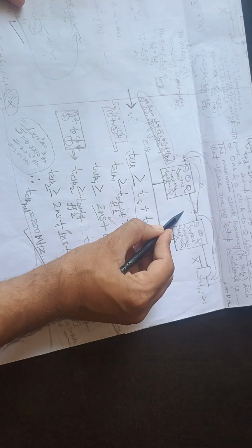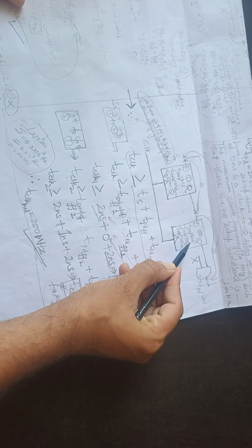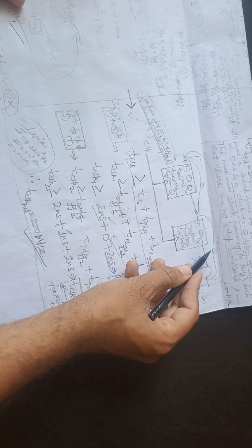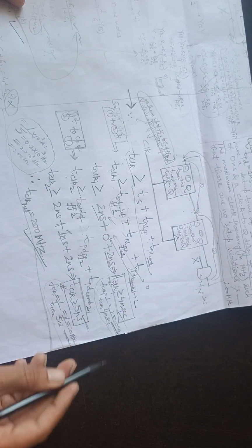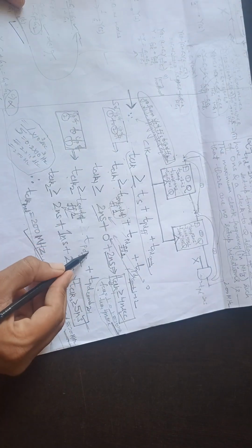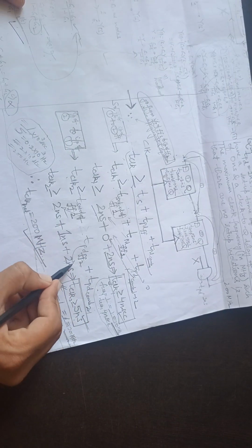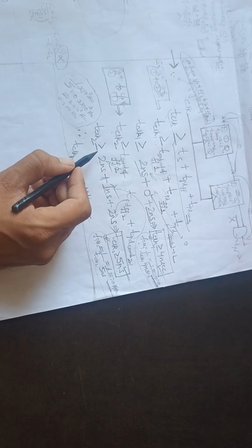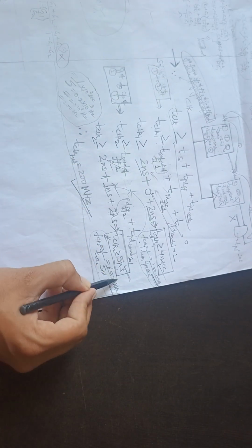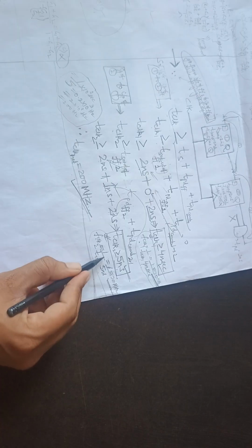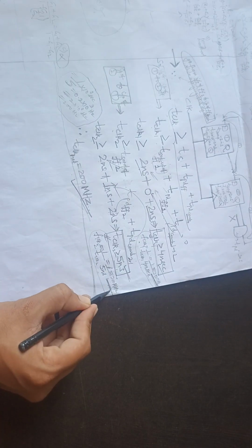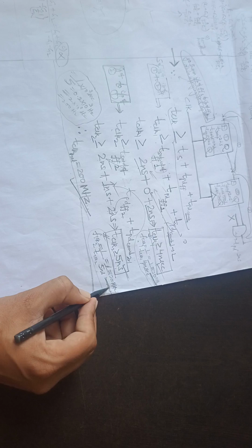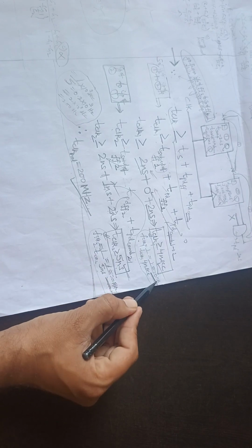Okay, and in the second case T clock 2 should be greater than or equal to the setup time of flip-flop 2 plus the propagation delay of flip-flop 2, and then the combinational circuit connected from 2 to 1. So setup is 2 nanoseconds, propagation delay of flip-flop 2 is 2 nanoseconds, and propagation delay of the combinational circuit is 1 nanosecond. So T clock 2 should be greater than or equal to 5 nanoseconds. So F clock 2, which is 1 upon 5 nanoseconds, is 200 megahertz. So this is maximum 200 megahertz, and this is maximum 250 megahertz.